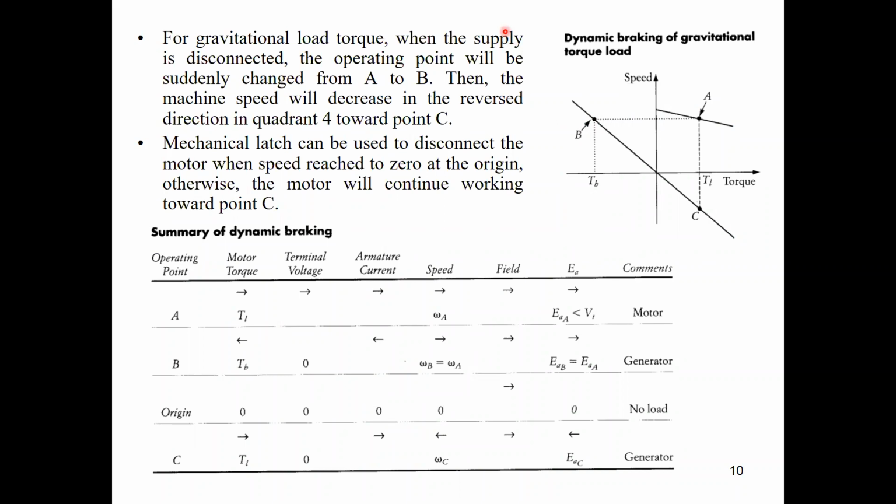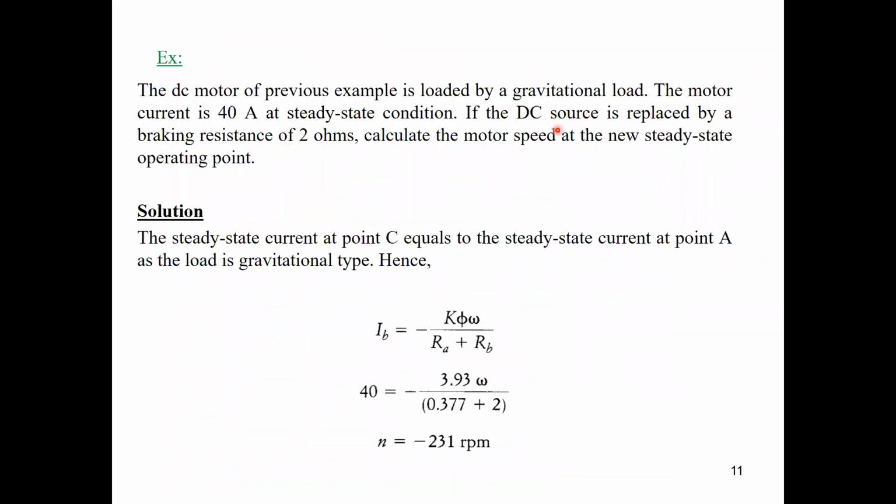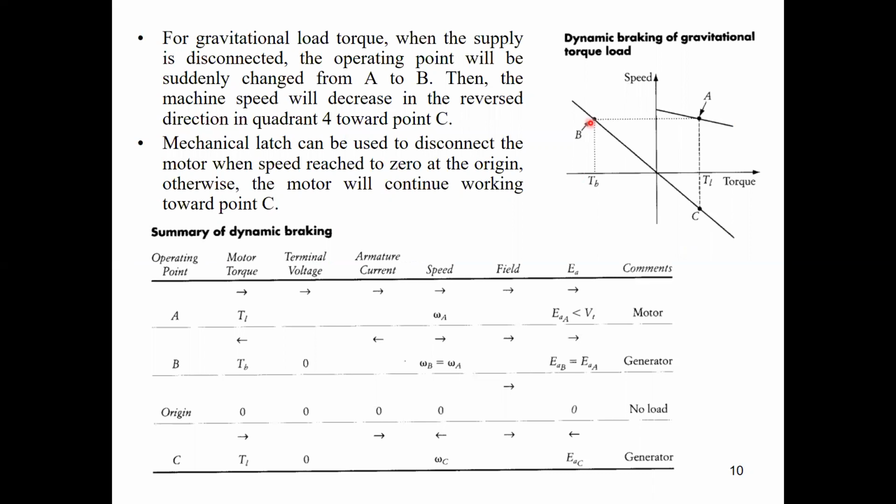Because the motor will try to reach the torque applied by the load. Okay, it's right, but what is said here in the problem to say that? As you can see, steady state. Yes, the word steady state. Because point B is a transient point. Is it right? Point B is transient, and point C will be the steady state point of the machine.